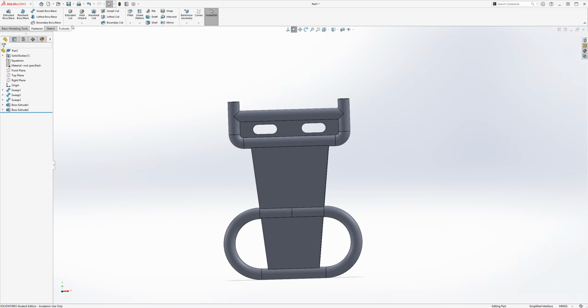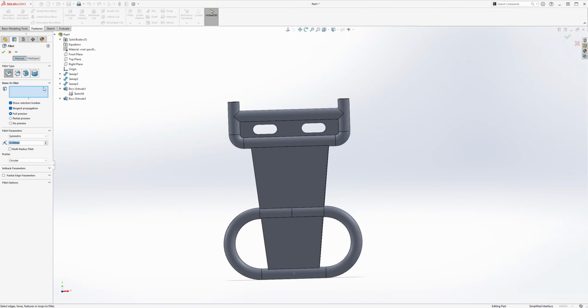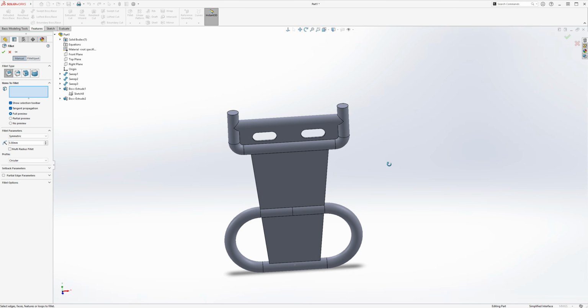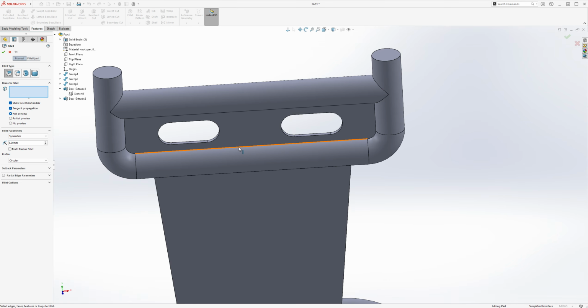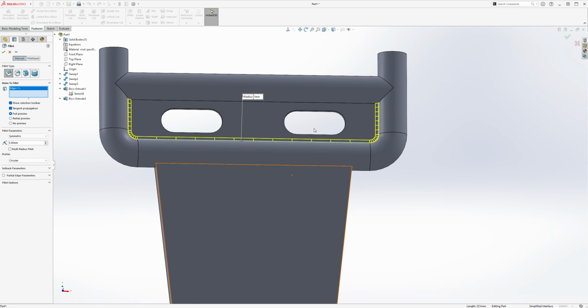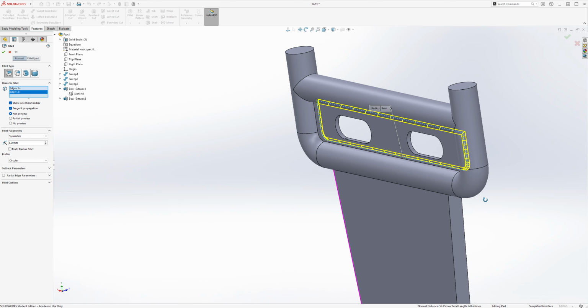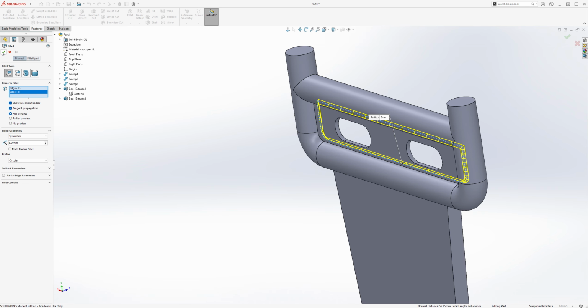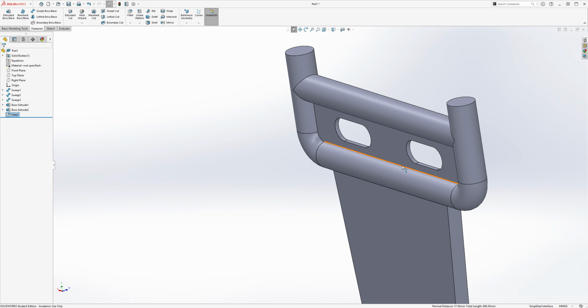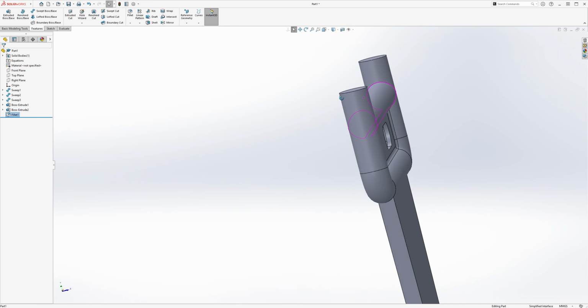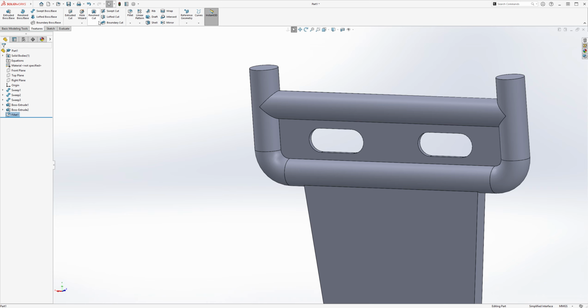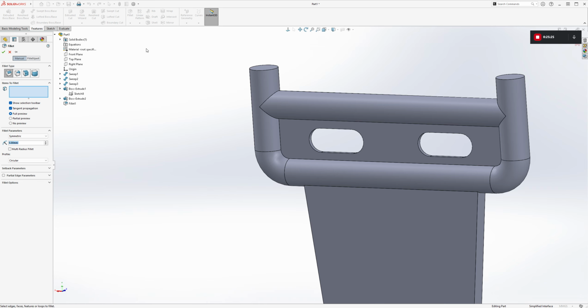Okay, now all that's left are fillets. So let's go to fillets, R5. R5 all fillets. So basically any edges you see, so this edge, top edge, select OK. I want to do the same thing for the other side.